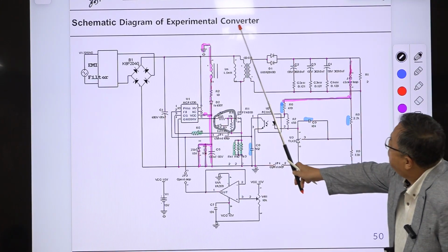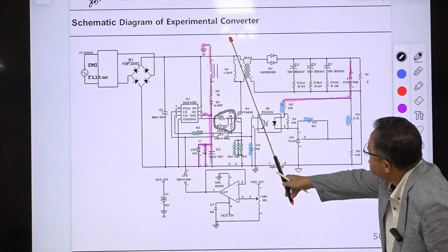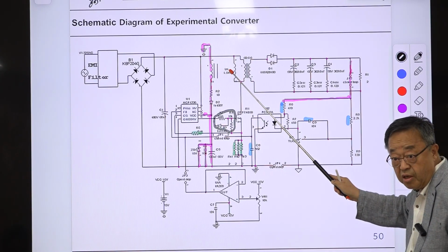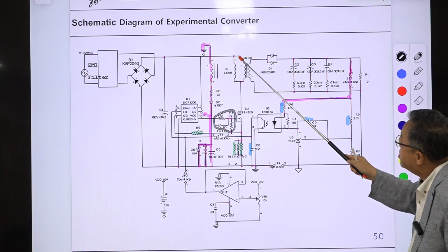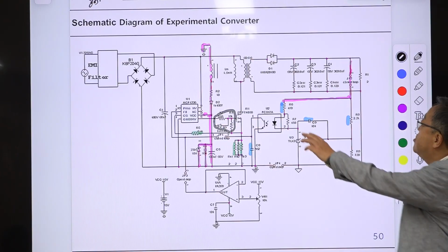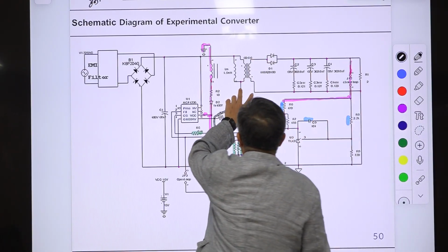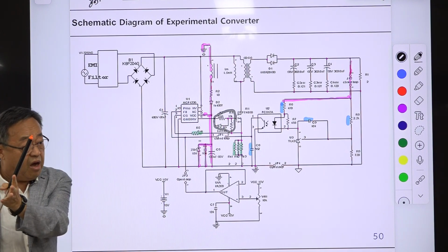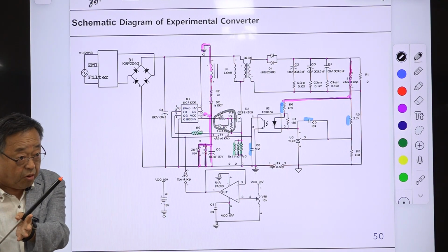During the on time period there is no current, so the inductor can be moved here. And during the off time period, this is connected to this port. Assume this is a 1-to-1 transformer, then it is the same as the output part of a boost converter.